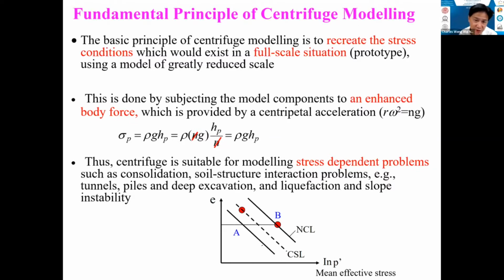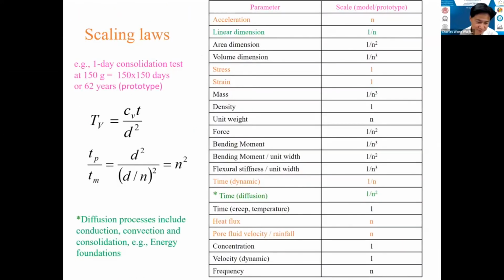That means we will be on the unconservative side versus the actual stress in the field, which we can represent by point B. There is a high stress. Actually, when you shear B, then you contract towards critical state. So we get the opposite result, but on the conservative side. That's why we must get the stress right before doing the experiment.